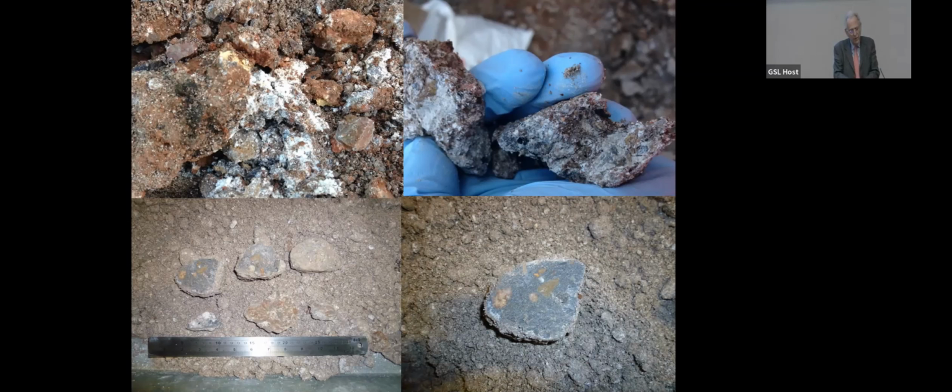Major new development: gas man installs or checks the gas main, checks there's no leaks, discovers gas under the floor slab, thinks it's him, checks again, finds it's actually hydrogen from the incinerator bottom ash. That's the sort of problem we're going to see, where it'll be discovered by accident, but it's gently evolving.